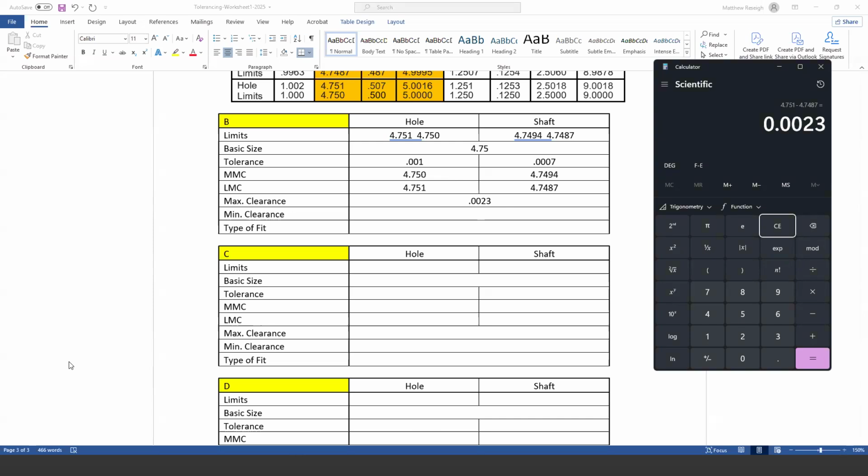There might be some test questions where they ask this, because if it has the zero in front of it, I should infer on a print that it's a metric dimension if I'm carrying the leading zero. That's confusing, but that is one identifier on a sheet by ASME standards. To choose that, though, I'd have to ask, is the company even following those standards? They may have just done that out of habit and not realized they were implying a metric dimension, or a standard they're not following.